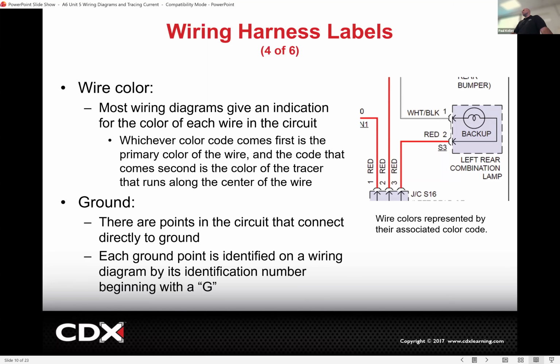If it was that easy, they'd be like, I don't need you, I'll just go look for S16 myself, but they can't find it. And a lot of it too is information. If you don't have the wiring diagram, you have no chance. If you don't have the wiring diagram and the component locator, you don't know about S16, you don't know where S16 is, and you have no idea what to do.